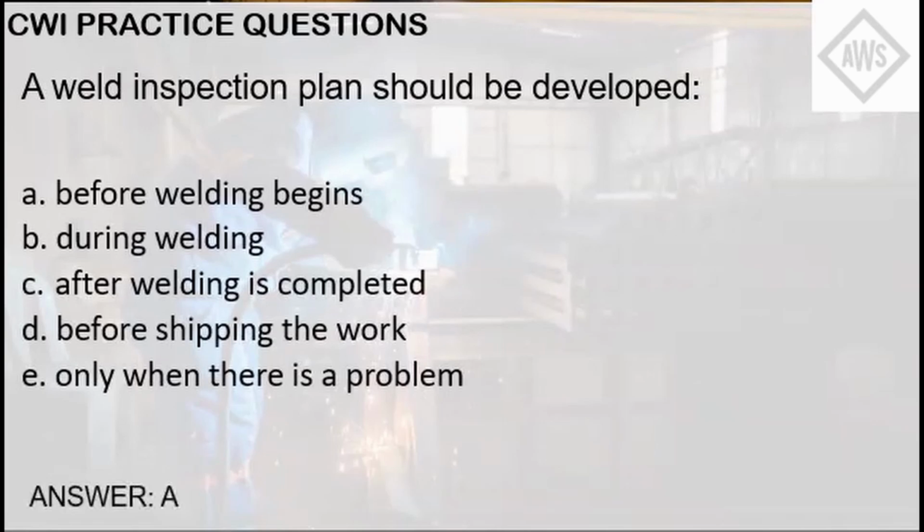Similar to an inspection test plan, which must be approved prior to the actual inspection activity. This inspection plan also defines the hold points in which the welding inspector will inspect the result of an activity. For example, the root pass will not be able to proceed to the next activity if and only if it yielded a positive result. These hold points will be difficult to implement if these inspection plans are done anytime after the welding activity begins.